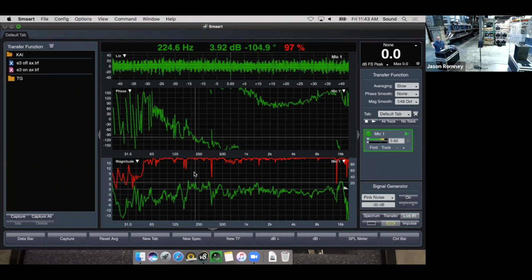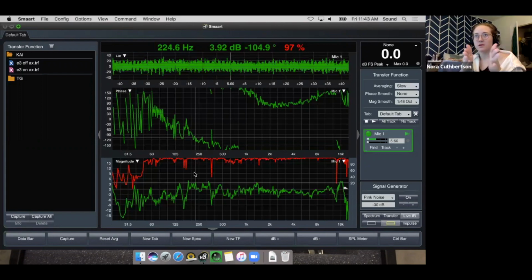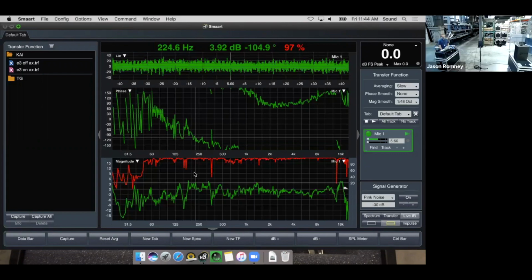The main argument that I hear that is convincing to me about why you should avoid this much smoothing is that this much smoothing has a tendency to hide comb filtering. Okay? If you think about that for a second, hopefully that would make sense to you. Well, because it's the exact octave that it smooths out. Yeah, so it's hiding comb filtering, and it does do that. And if you have some comb filtering going on because of some problem with your system, then this will hide that.